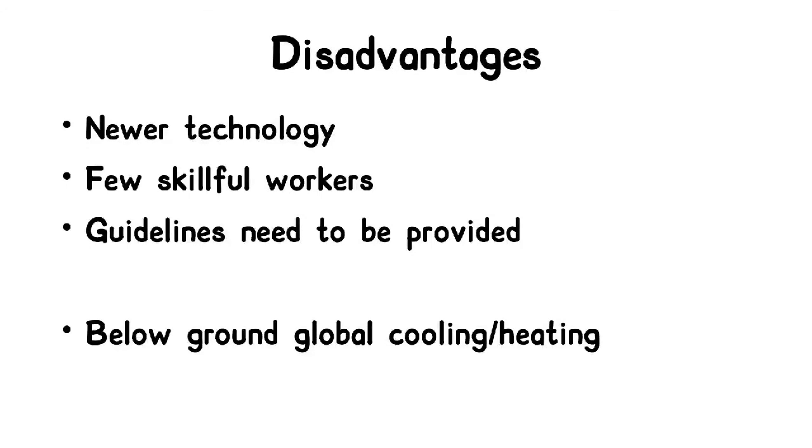If you are extracting the heat from the building and putting it in the ground, there should also be extraction of heat from the ground and using it somewhere else. Let's say, if you are in a tropical location, you can extract the heat from the ground and heat up water.